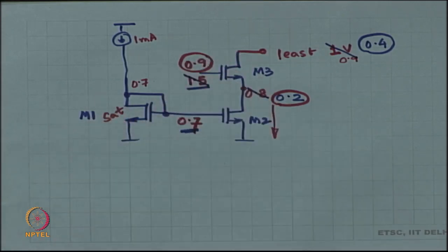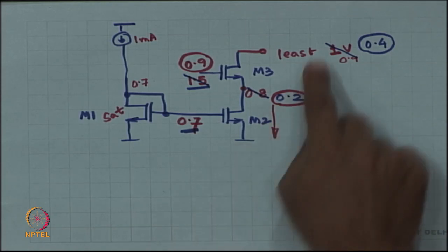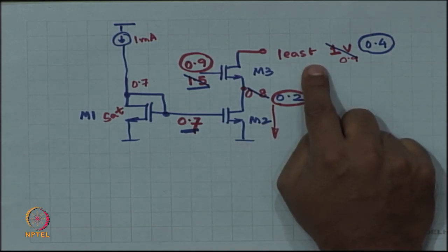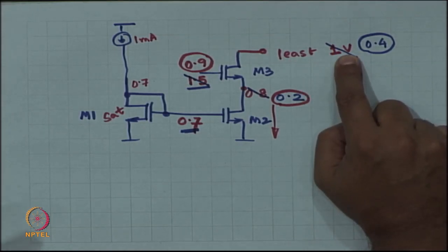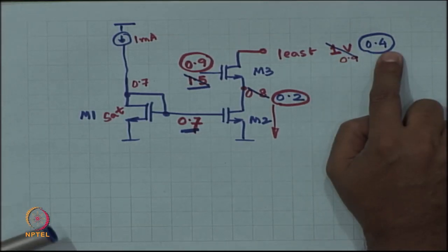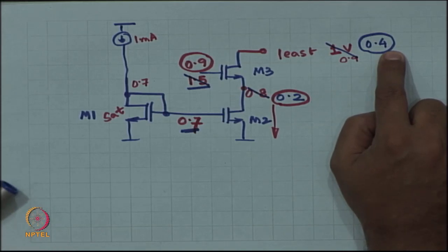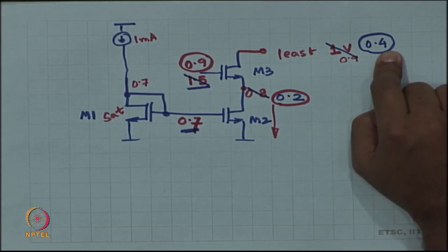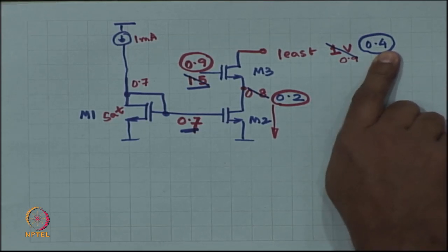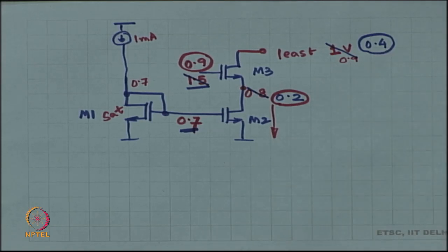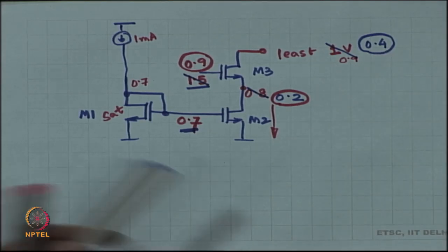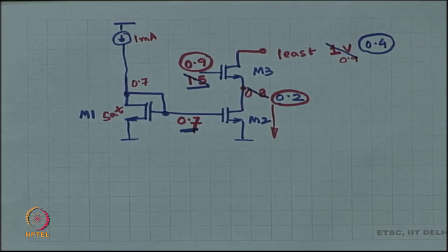On one case you have a positive, an upside, right, that you have got graceful degradation. On the other hand, you have a downside, that the range is much more limited, right. And in this case, the upside is that the range is much more, the voltage range, the headroom is much more. However, there is no graceful degradation. As soon as you cross below 0.4, you are done for. Okay. So, these are the pros and cons.